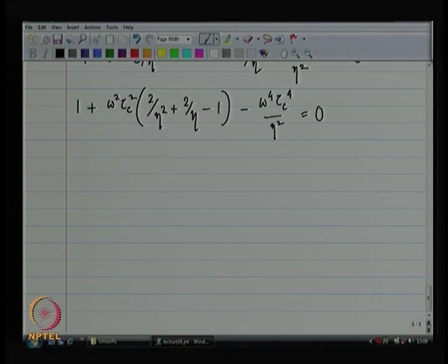So, I have got a quadratic. So, let me recast my quadratic with the appropriate signs. So, I am going to put plus over here, minus over here and minus over here, and actually it does not matter. Okay, does not matter. Let us solve this for omega, and that should give me my bandwidth. Can I solve for omega or omega squared? It is a quadratic in omega squared. So, in the first step I will just have to solve for omega squared, and it is going to give me 2 roots for omega squared. Which one are you going to take? It is a good question. Let us hang on a little bit.